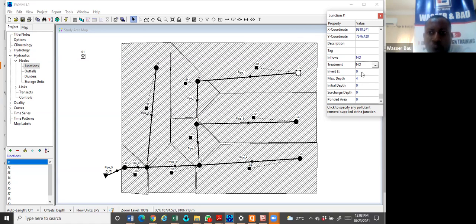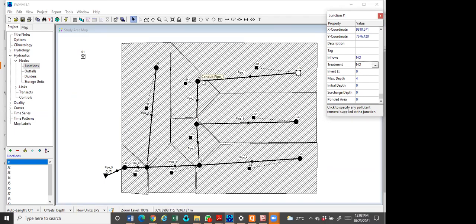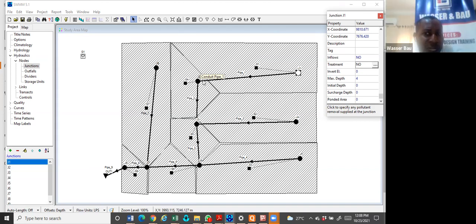And what we'll do now is let us have a reference. In real life, in real design, the surveyor will give you the invert level at all the nodes. That's the standard. Remember, the job of the surveyor is to give you the invert level, the spot height, and that is what you need to compute the elevation. Why you need elevation is so that you will know the direction of flow.